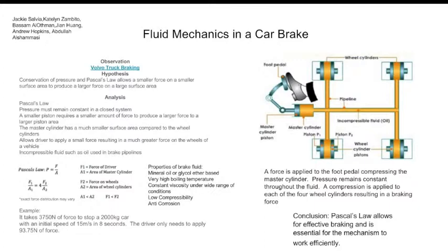Analysis of the brake system specifications and the fluid mechanics shows us that the hydraulic brake system effectively multiplies the force applied by a driver's foot by 40 times. By using the appropriate measurements and equations, a small amount of force applied to the brake system translates into a very large force that could bring a 40-ton truck to a complete stop in mere seconds. This simple, yet effective mechanism plays a large role in our everyday lives, allowing for both safe and effective performance in driving.